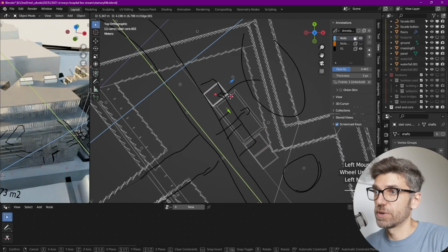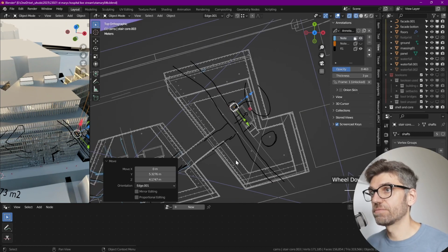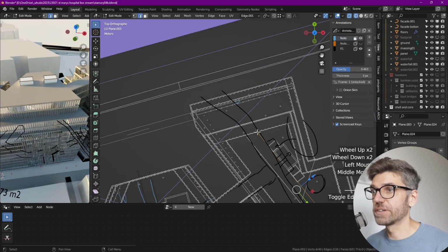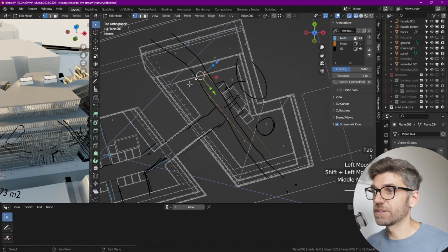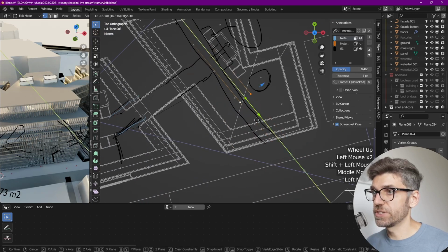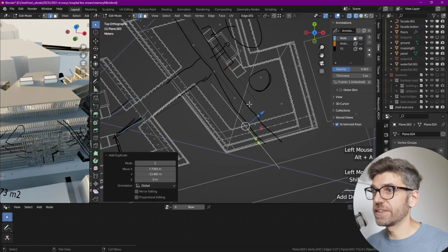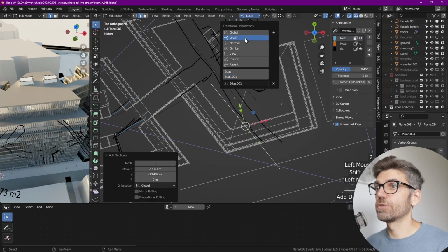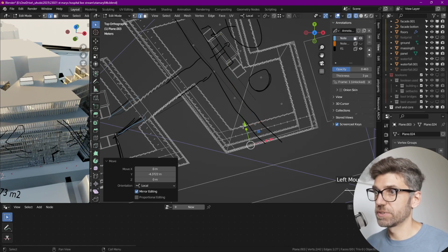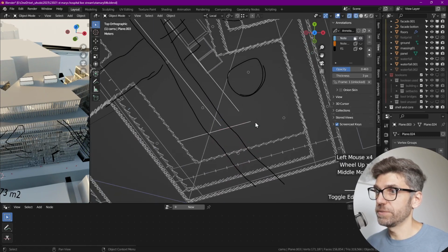Okay, so and then we're going to put that over here. Not ideal, not terribly happy with that, but I think for now that's the setup, the layout that makes the most sense. And now let's start to push these inwards. Duplicate that. Let's go to local orientation, scale it along the Z, start from this edge, and now let's move to somewhere over here.